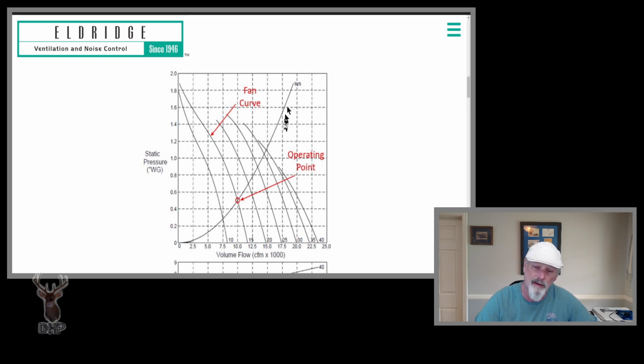We can let the system curve represent the pressure that we would build up statically and dynamically in our little computer box versus the ductwork in the system here. But what we do see is when pressure is 0, we have high flow rates right here. Right? When pressure is high, say at 1.8, we got no flow for most of these operating points, none at all. Some of these fan curves at different pitches, I think that's what these are, pitches of inclination.